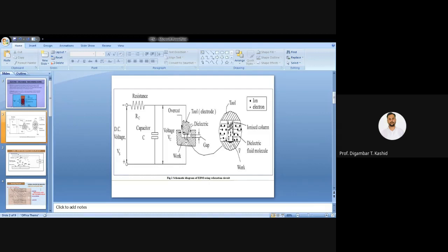You can see here, or here also, in this manner, the craters are where the metal was molten. This much metal is removed from the workpiece surface because of the huge heating, so it forms craters on your workpiece. You can see in this diagram that I have shown the craters. These hemispherical craters are generated because of a single spark.